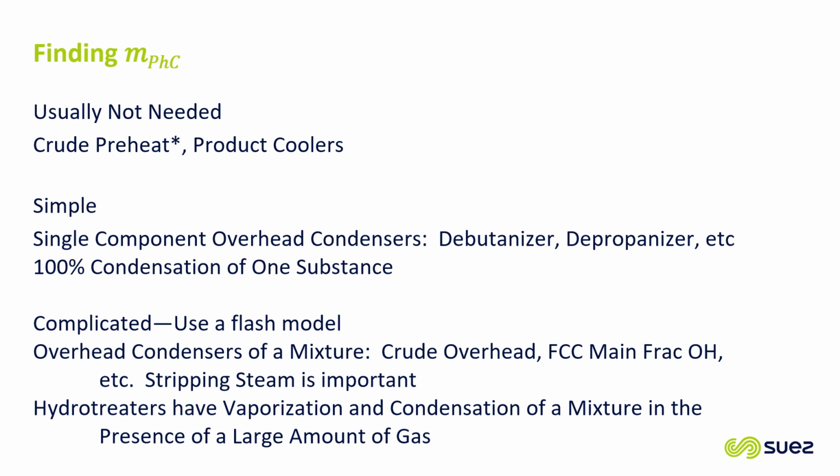One of the reasons we've talked about the various constants that we use is to make sure that we can compare apples to apples with our process engineering customers when we talk about the results. So if we're trying to tease out why our numbers are a little different from theirs, we want to know the area of the exchanger, we want to know the heat capacity that we've used, we want to be able to discuss those in depth.